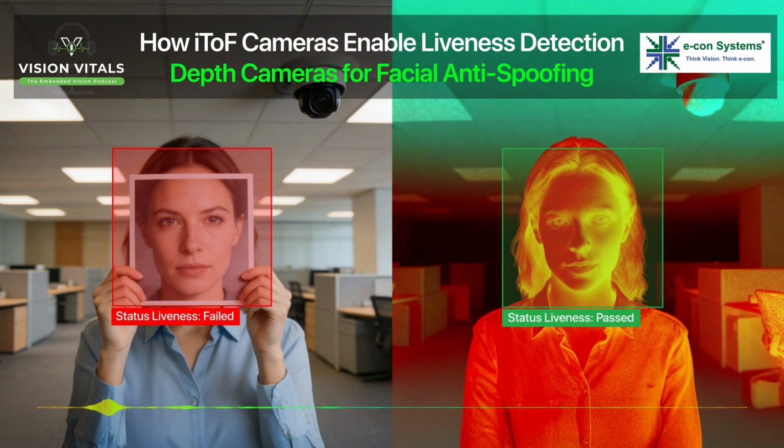On the illumination side, it uses 940 nanometer near-infrared illumination, which provides stable depth capture across low light and high-contrast environments. That directly addresses the lighting stability requirement. And the output streams? Depth Vista Helix provides synchronized depth, IR intensity, and confidence maps, so solution providers can use one or a combination of those streams depending on their algorithm design.